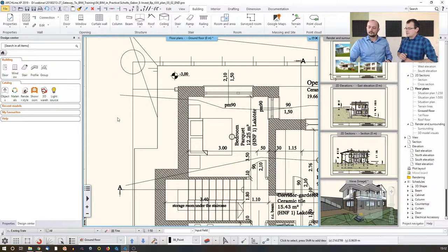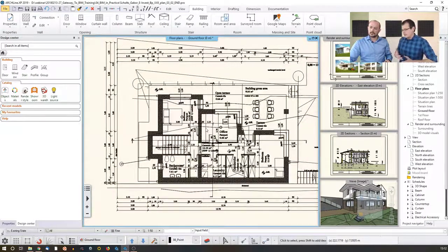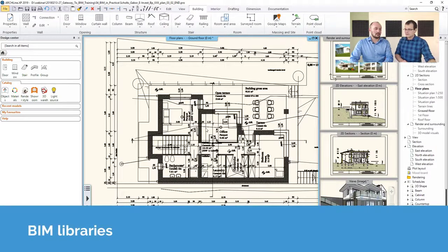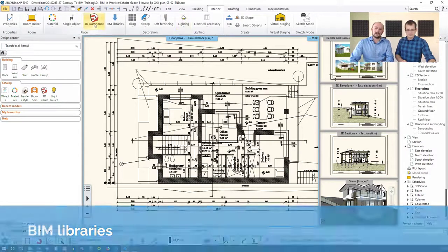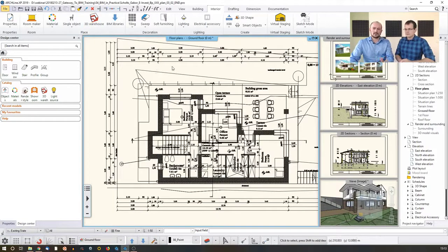Yeah. Now let's look at the exact example of where the BIM workflow comes in, because so far we talked about storing information, but what about bringing information into the plan? I think the first step would be the BIM object and element libraries. If you are about to enrich your model with any sort of data from certain libraries, you will likely go to those libraries that you can find here. Either here, the 3D Warehouse is a popular option, but those are not BIM objects. Those are just objects. They're only the material, the surfaces, and how the object looks, but there's no extra information stored in it like price or maker or anything else.